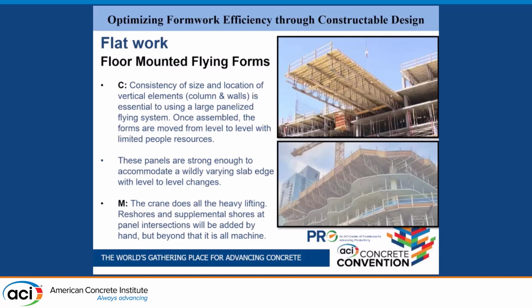So speaking of connecting things together, our next system is our floor-mounted flying forms, or truss panels, as many call them. These things are great. If I could put these on every project, I absolutely would. They fill a full bay. You get up to 90 feet, or maybe a little bit more, long. You pick them up with the crane, you fly them out, you put them right back in.